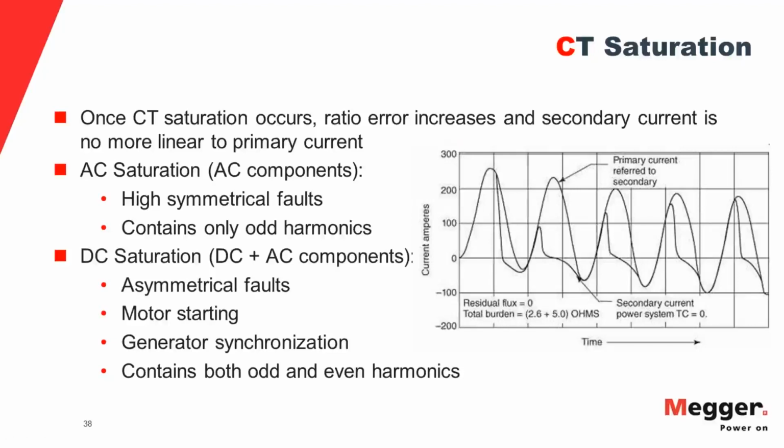Now, when I talked about the tap changer, I said that I will cover later in detail what exactly the percentage restrained characteristics are. So we discussed all the challenges so far. We discussed current mismatch caused by CTs, phase shift issues, zero sequence issues. We also discussed tap changer problems and CT accuracies.